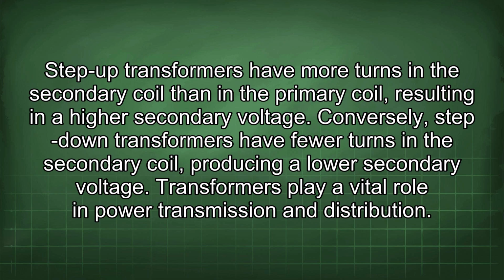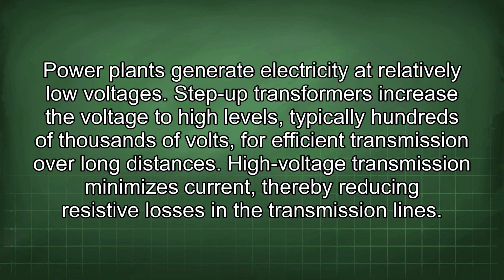Transformers play a vital role in power transmission and distribution. Power plants generate electricity at relatively low voltages. Step-up transformers increase the voltage to high levels, typically hundreds of thousands of volts, for efficient transmission over long distances. High voltage transmission minimizes current, thereby reducing resistive losses in the transmission lines.